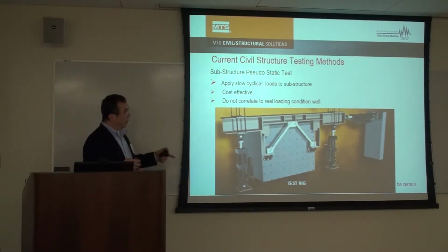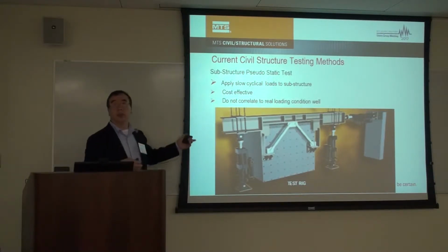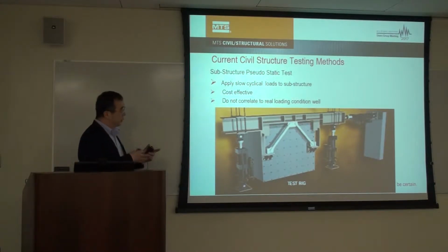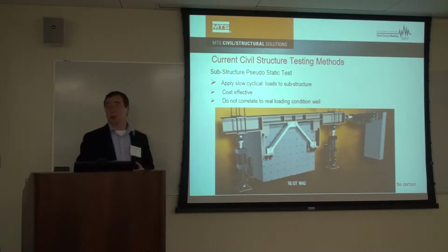The good thing about that is it is simple and cheap, and it's a component test. But the bad thing is the loading is not realistic. The simple triangular wave shape is not a real earthquake.